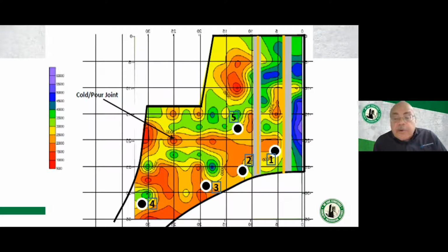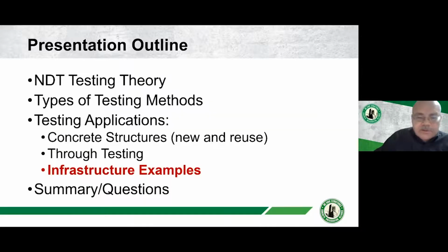This was an outer ring, an outer slice, showing some of the weaker concrete, slower velocities, the oranges and the reds. You got in 18 inches, 2 feet, everything was blue and purple, 5,000 PSI, 6,000 PSI, salvageable. No reason to demo this, chip this concrete out. They can certainly salvage it. It's always cheaper to repair a structure than replace a structure.